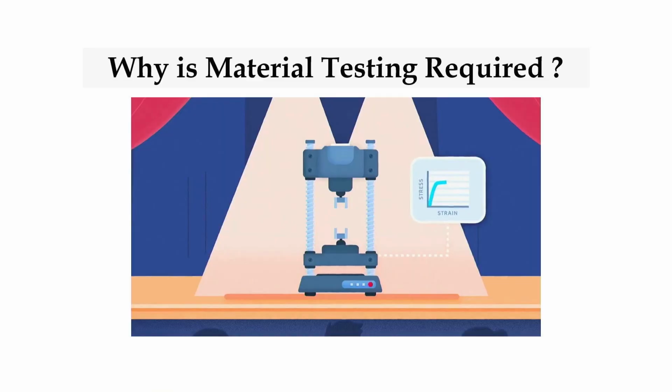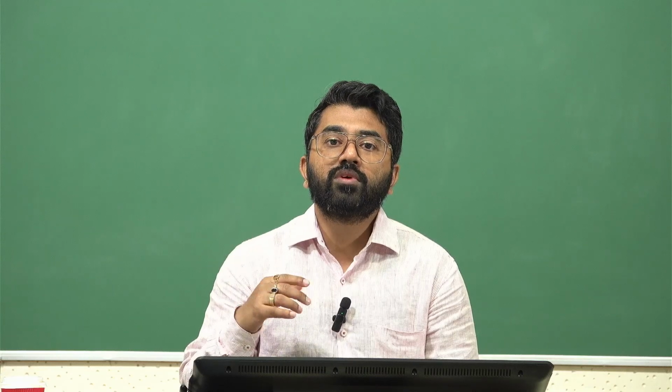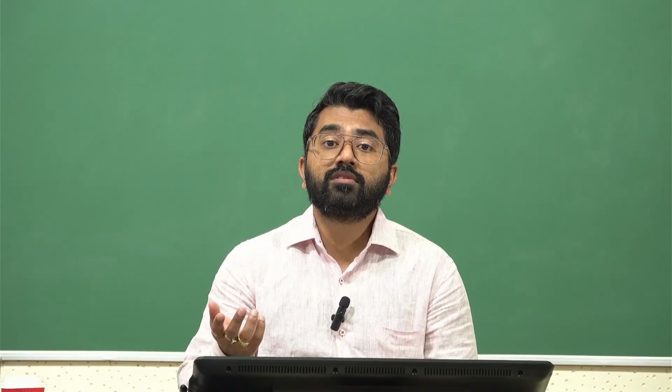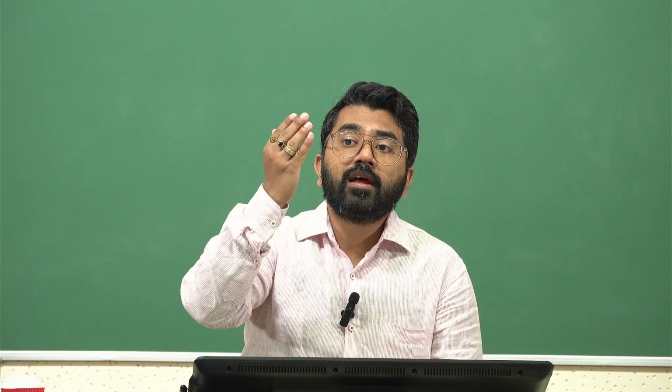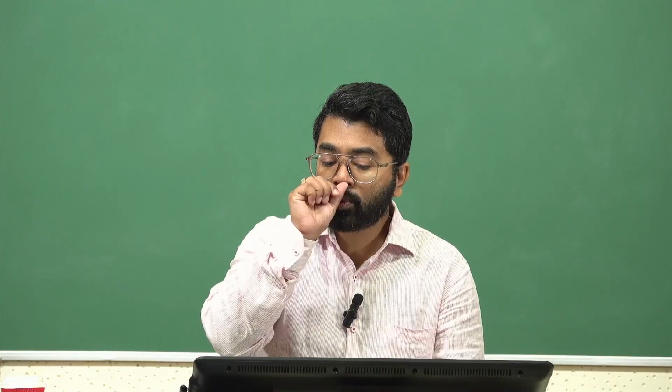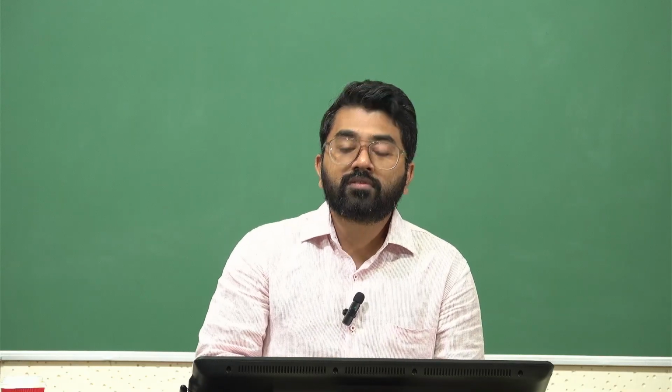So typically what you get out of a material test is a very important thing, and we want to revisit this a few times just to make sure this is very, very clear. So the major reason why you do a material testing or a soft tissue testing is to understand the stress versus strain response. This is the response we are going to talk about a lot, and I'd explained quite a bit in the previous sessions, where you basically get a load versus deformation data out of an experiment. Either you do a tensile testing experiment or a compressive testing experiment, and you use that data to generate a stress versus strain profile.